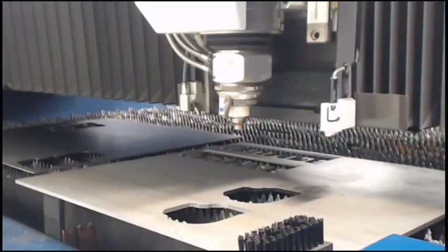And usually, it depends on what your welding process is, but you can usually weld it as well. If it were a laser weld or something where you have a very low heat zone, you have to use nitrogen. You're going to have bubbling and popping. But for a MIG weld, where you can spread that, quote, contamination around, you won't have a lot of porosity or issues with consistent contamination within the weld root.